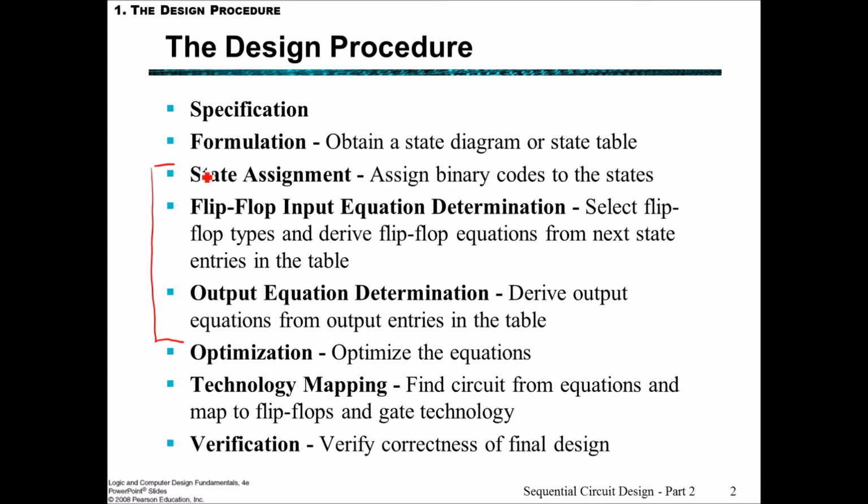We need to do a state assignment, which is something new, which is to assign unique binary codes to the states themselves. Then we have flip-flop input equation determination, which is a long way of writing what are the inputs to the flip-flops, remembering that we can use the flip-flops as storage elements to store the states. Then we do the output equation determination, where we derive the output equations from the entries in the table.